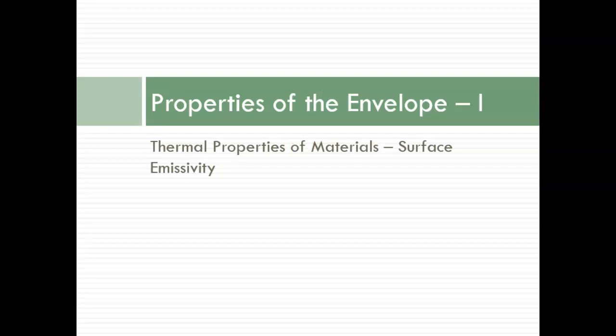So far we've discussed conductive heat transfer, the dominant mode in most building assemblies. The other 2 modes, convection and radiation, occur only in air spaces that exist in walls, roof ceiling assemblies, floor assemblies, and insulating glass units.